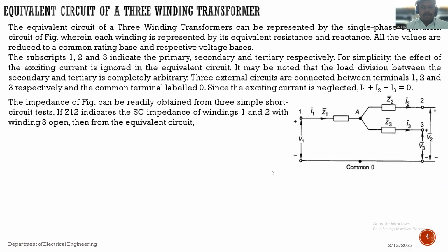Okay, see, it can be considered a single phase equivalent circuit, and according to this we are deriving the three winding transformer equivalent circuit, which is shown in the figure, wherein each winding is represented by its equivalent resistance and reactance.